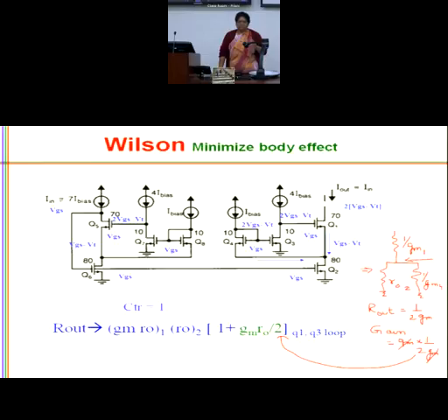So it is always coming in between 0 to VDD. If it is consuming too much headroom, if the voltage requirement is too much, then the voltage range available for the amplifier to work reduces, which affects its swing, which I do not want. Because for me, biasing is not taking part in dynamic operation. It is only providing a bias. So I need to design the circuitry such that it takes very little voltage.